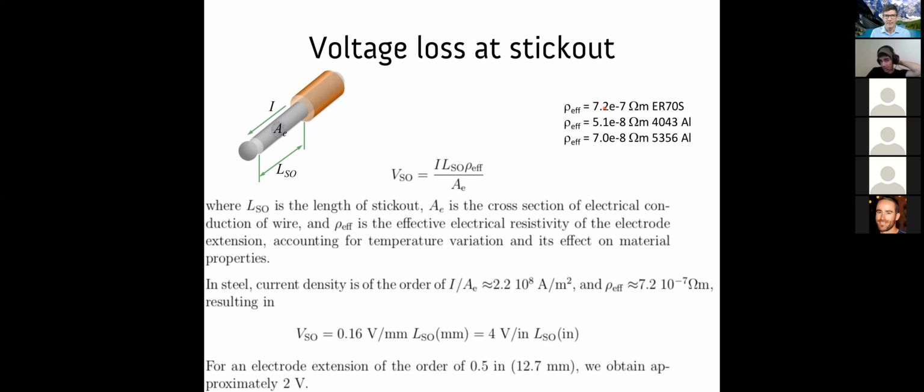Has more manganese to suck up the sulfur or the oxygen, has more silicon often, right? Has a little bit of titanium to generate this acicular ferrite we like so much. For that reason, if you try to approximate resistivity using a tabulated value from a book for a random steel, you tend to be low. But we measured it for welding wires.